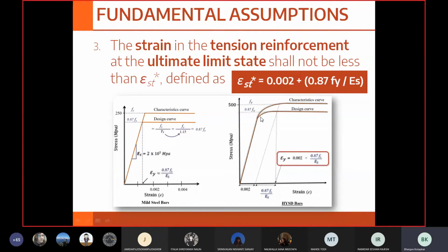So at the same value of stress, it can undergo a lot of deformation. We have seen it in the stress strain curve for mild steel in the previous semester, wherein the breaking strain was about 100 times the yield strain. So it can undergo a lot of deformation in its inelastic state before actually collapsing.